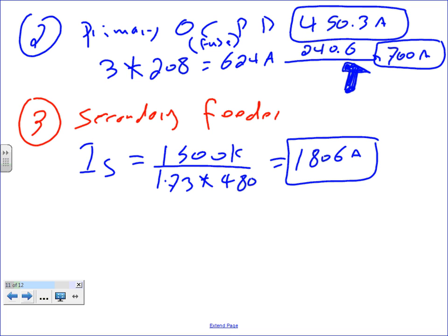Okay. So we need to size the conductor though. That's not enough. 1.25 times. Now where would you find this one? 215.2(A)(1). That's what it tells you to do. It's a feeder.